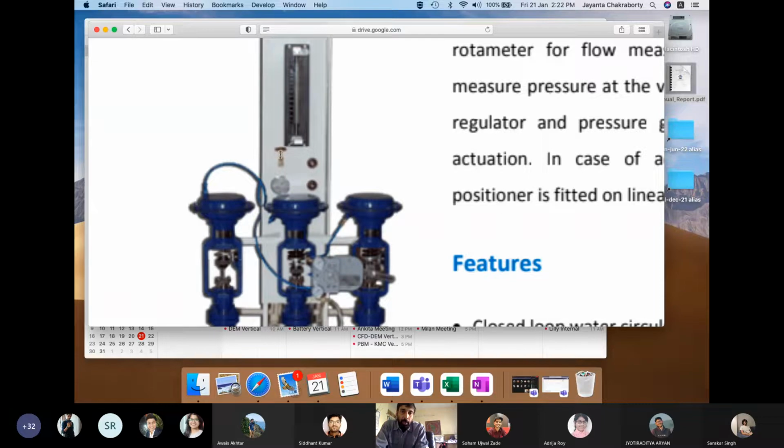So this is a vent valve. If you open it completely, it will drop. If you close it completely, it may go slightly above 20. So we just open it slightly so that the supply pressure is maintained at 20 psi. So a small bleed is allowed from here. We maintain 20 psi. This is a pressure gauge, a dial. It will show you 20 psi. And these two knobs you can change and then change the pressure here.